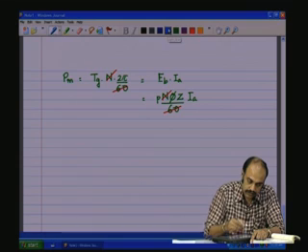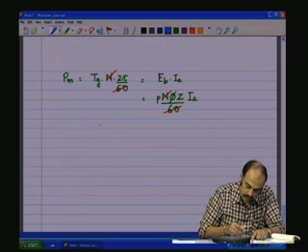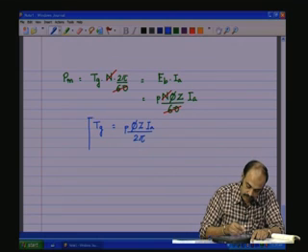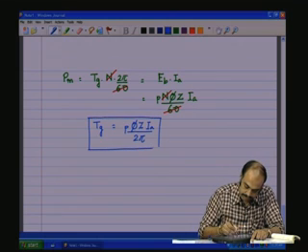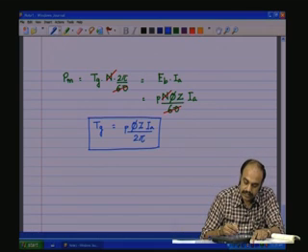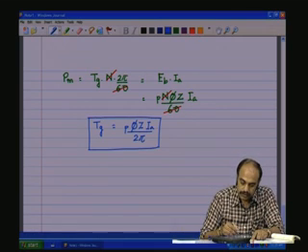So, this would result in the generated torque Tg, which is number of pole pairs, flux per pole, number of conductors, Ia by 2 pi. This is the equation. So, you see that number of pole pairs, phi, z and 2 pi of course is a constant.